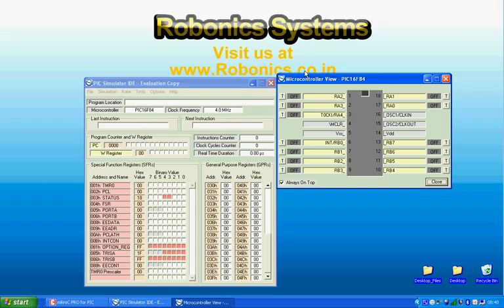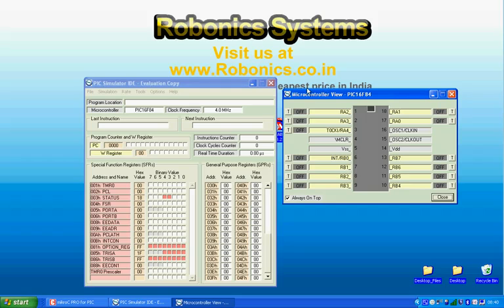Now let me explain this microcontroller to you. PIC 16F84 or PIC 16F84A has basically two ports, port A and port B. Port A has 5 pins, RA0 to RA4, and port B has RB0 to RB7. You also have the power supply, VSS and VDD, and you have MCLR. MCLR is something specific to PIC. You have to pull it high with a 10K resistor in order for the program to start running. And this is the clock oscillator, where you give the clock pulse input.